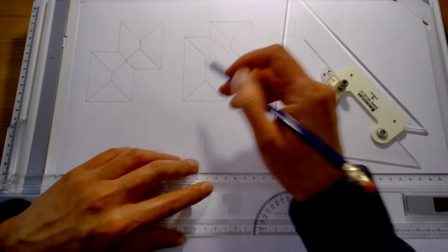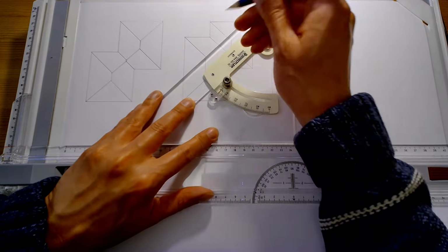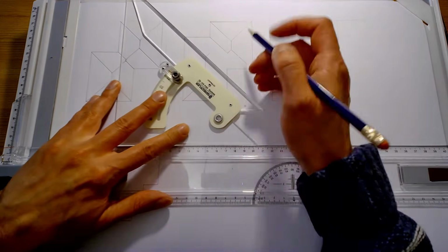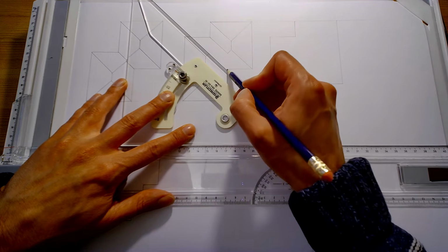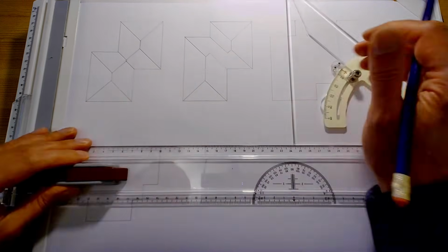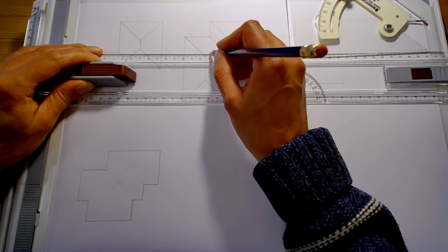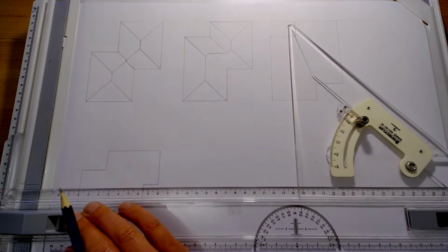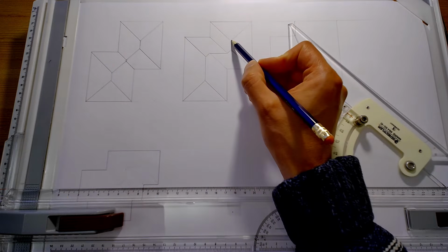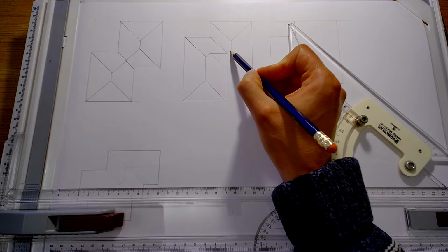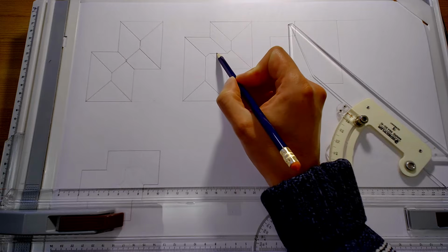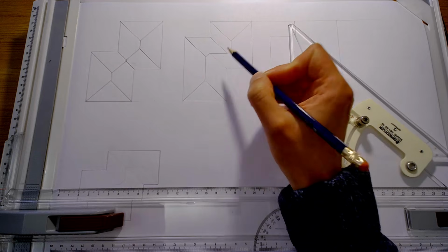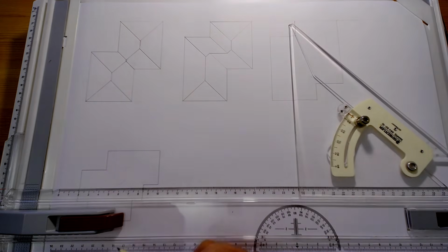Okay, so we've seen they've connected up. Then we will just draw a hip going down there until it meets this valley. And then we can just do a ridge line going between those 2 points there. So now we can see that the ridge is along here, a hip drops down to there, a ridge runs across, and then a hip rises back up to this ridge here, with valleys there and there.